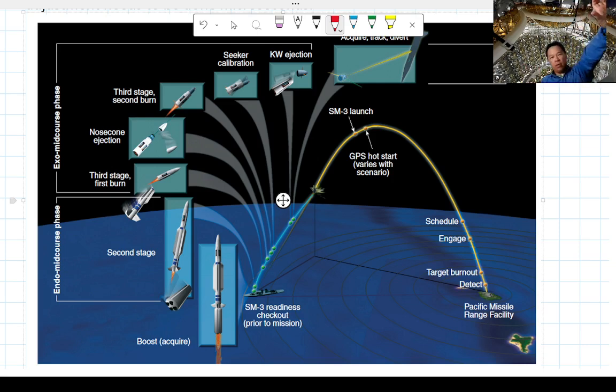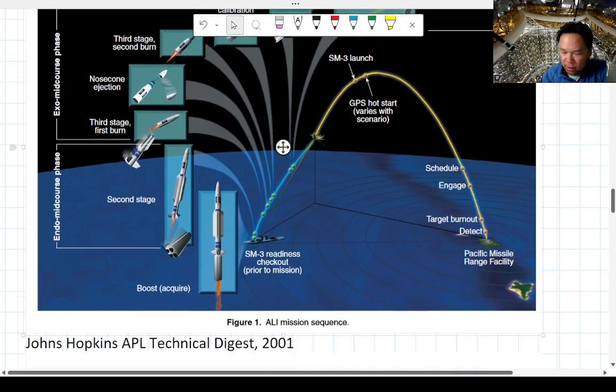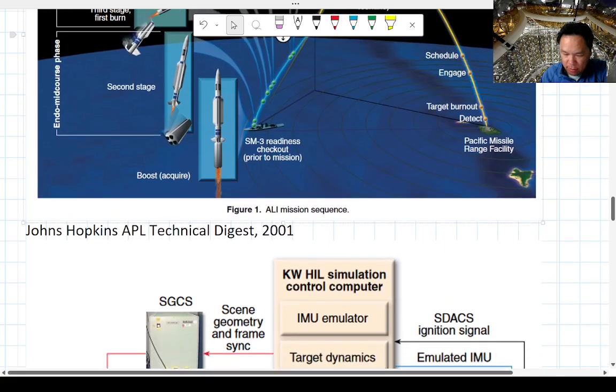You're using a camera that has some pixels on it, and that's actually able to detect which direction the target is in, right? You want to convert that information from analog to digital as fast as possible. Do a little FPGA to do a guidance program in it, okay? And then send that feedback to your fin so you can direct things in the correct way, so that you are homing in on the target, okay?